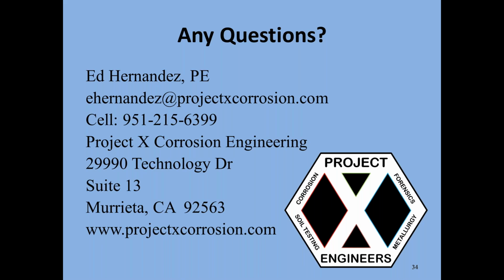So there is something like AWWA C105, which has a nice chart for determining if a site is a bit corrosive to ductile iron, cast irons. But that's very specific for iron. And then usually the Army Corps of Engineers, I think, or even NASA. NASA has some great stuff. The Navy has a lot of stuff on corrosivity and trying to simplify these things. But again, you have to keep in mind what material you are worried about.